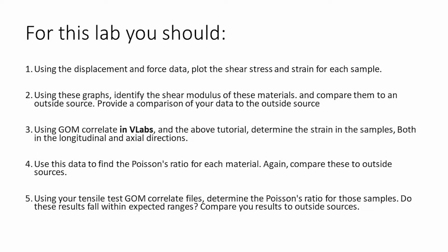For this lab, we're going to break the analysis into three parts. The first, and probably the simplest, is going to be to take your force and displacement data and generate a series of plots for shear stress versus shear strain. Using these plots, you'll be able to identify the shear modulus of the material. We want you to take that shear modulus and provide us with some commentary about why it does or does not match the existing records or literature for the shear moduli for stainless steel and copper.